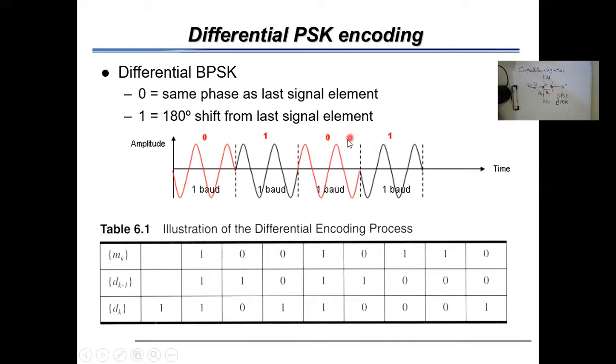And you have a correlation between this bit and the previous bit, because now this bit, which is the 0 bit, is coherent. So for example, the signal starts with a phase of 180. Whenever you have a 1, then you change the phase, so you return it back to 0. Whenever you have 0, then you have the same phase. Whenever you have 1, you change the phase, and so on. So this is what we call differential phase shift keying. This is the differential phase shift keying technique.